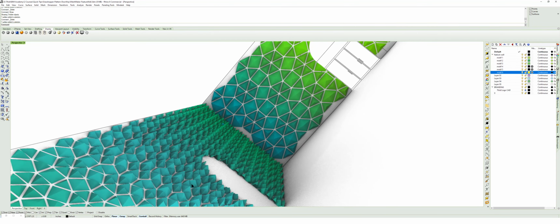Okay. So go ahead and go over to Mesh Plus, go down to Make, and then select the rhombic trihexagonal tiling. That is a mouthful. And you can explore various different tiling options, but I'm going to explain how to set this one up. Plugging your surface into the S, and then what we want to do to get the U and V count, rather than an arbitrary number, we want to get it based off of this grid that we've created here. So in order to do that, we want to get length. So type in length, go to list length, plug that in.